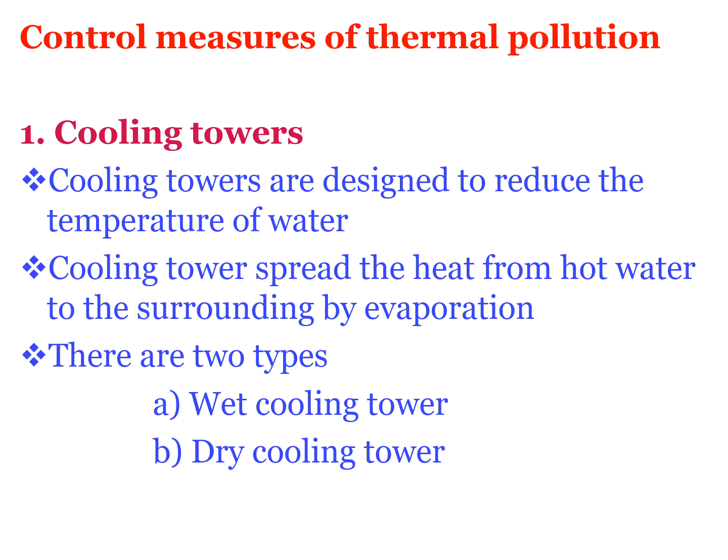Here the cooling tower spreads the heat from the hot water to the surrounding atmosphere through the process of evaporation. So here is what actually happens. Hot water from the industrial process is pumped to the top of the cooling tower and distributed over the fill material. As the water cascades downward, air flows through the tower, either naturally or by mechanical assistance.